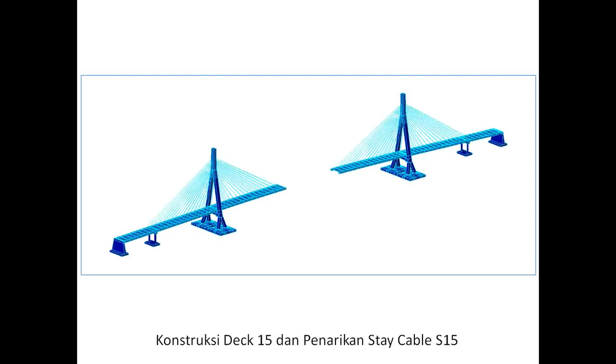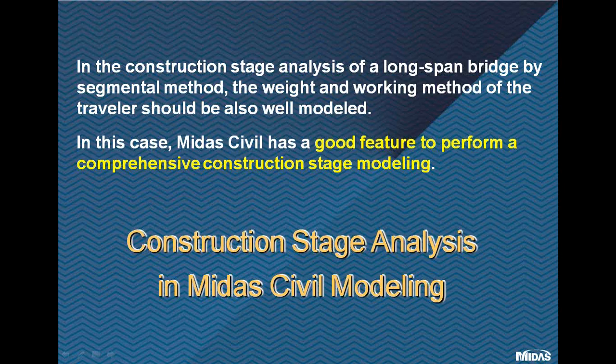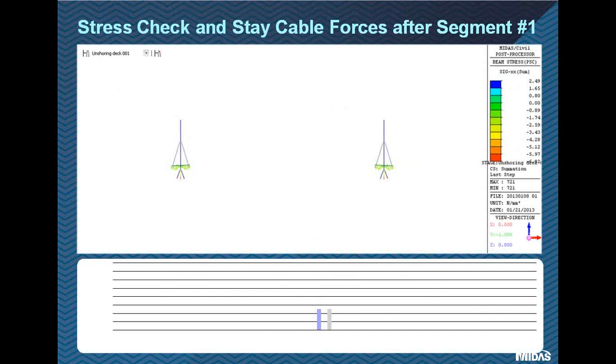In all construction stages, we analyze the variations of cable forces, bridge deck stresses, as well as the pylon and bridge decks deformation under all construction loads, including the traveler's loads, in order to make sure that all stresses and deformations are safe in every stage of the construction process until closure of the bridge deck and installation of the superimposed dead load such as asphalt, concrete, railing, etc. This is some outputs taken from Midas Civil showing the variations of the deck stresses and the stay cables forces.